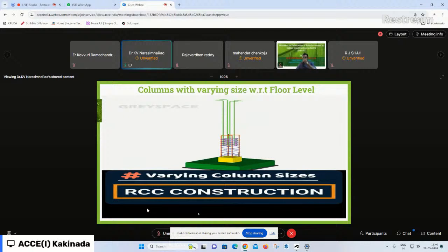We have seen a tapered column, with tapered reinforcement bars with a tapering angle of not more than 1 in 6. How it is to be tapered and the location of the tapering we have also discussed, along with a practical mistake that took place at my own construction site, which I explained in the previous part 1 lecture.